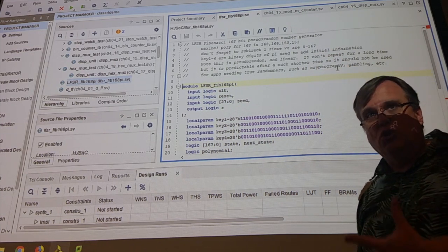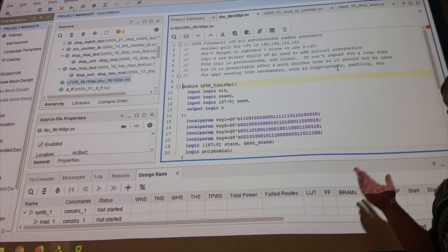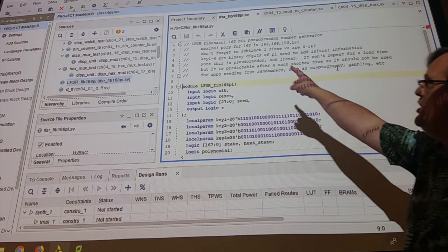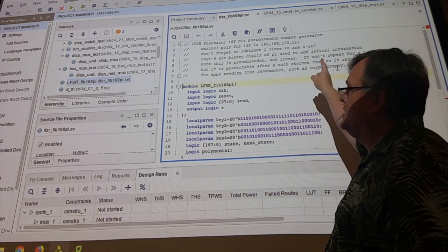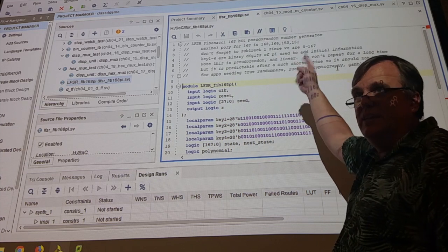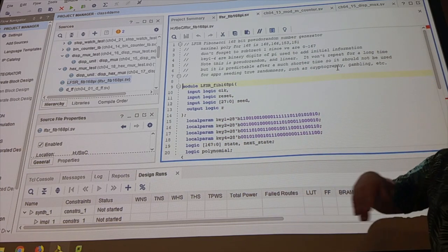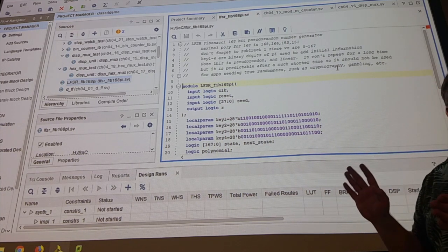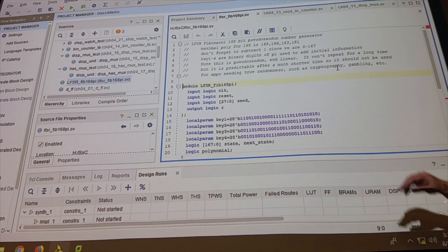Like I said, you can look these up online, and they just list them all. So I just looked them up. Those were the 4 taps I need. I mentioned here, don't forget to subtract 1, because our numbers are from 0 to 167. When they list the taps, they list them from 1 to n, not 0 to n minus 1. So you have to do the minus 1 manually, otherwise you're not going to convert right.